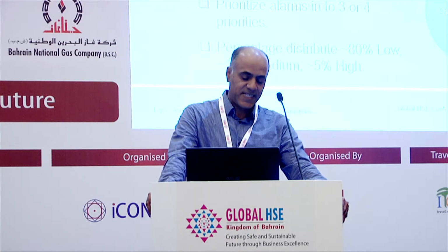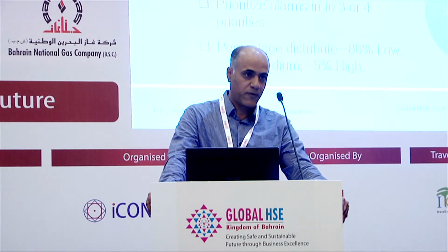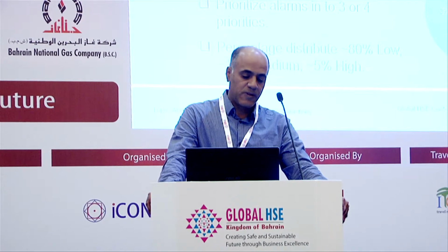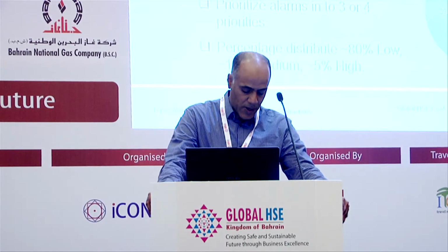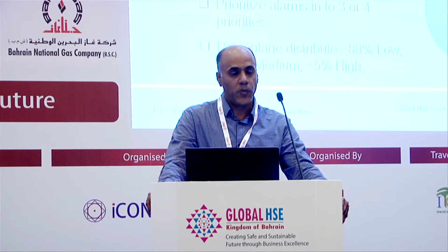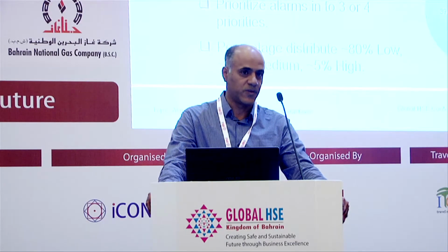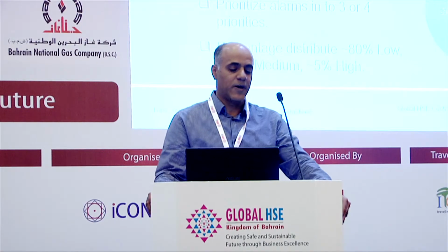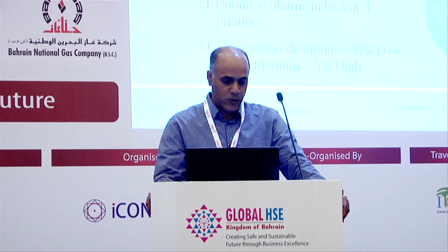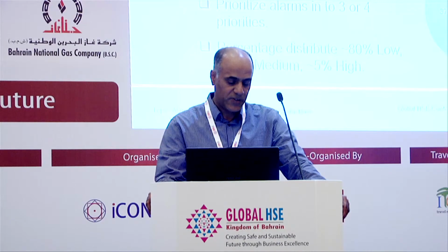Prioritize. Prioritization is a vital weapon for the operators and the alarm management systems. One of the problems found during the investigations of all the accidents I listed in the first slide was that the operator had no means to distinguish between what's important and what's not important. Everything appeared as high priority, and everything was generating so fast. So the operator had no means to make out where to go first. So this prioritization process will help to decide which alarm to address first.